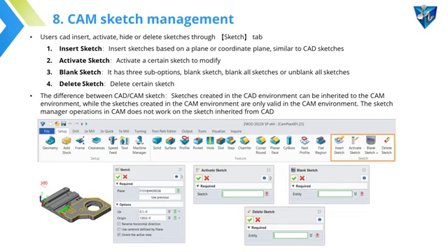Users can draw the customized profiles through Sketch function. And through Sketch Management, you can insert, activate, blank, and delete sketches. The difference between CAD and CAM sketch is that sketches created in GW3D CAD environment can be inherited to the CAM environment, while the sketches created in the CAM environment are only valid in the CAM environment. And the sketch management function in CAM environment does not work on the sketches inherited from the CAD environment.